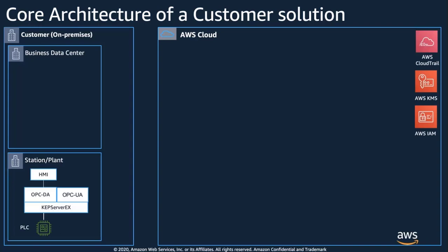From your PLC, there is usually a protocol converter, which is something like KEPServerEX in this walkthrough. However, there are quite a few other partners who play a big role there, so it's your choice. But in this walkthrough, it is KEPServerEX from Kepware, which helps to take the PLC protocol, which can be one of many, to a standard protocol named OPC UA.